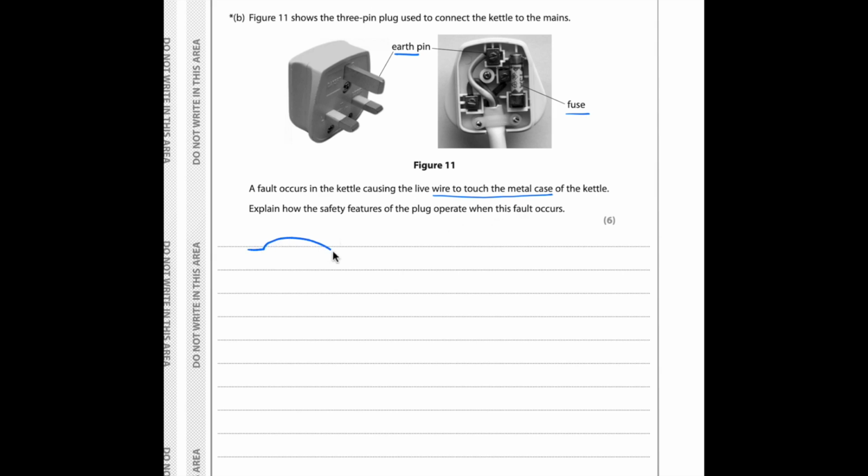If you look inside a kettle, it'll have a circle of resistance wire. Now if you've got the kettle here, there's the spout, there's the handle. Now if the kettle's working properly, the current will go all the way around that resistance wire. However, if this live wire, which is brown, becomes loose, the current won't flow around all that resistance.